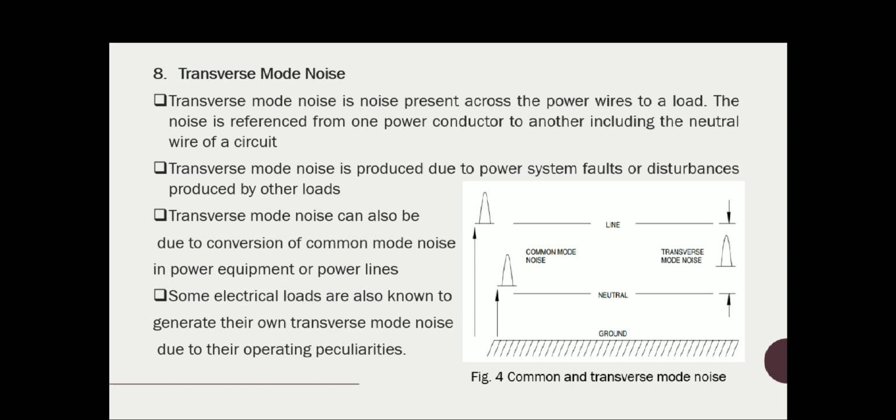Then transverse mode noise. Transverse mode noise is the noise present across the power wires to a load. The noise is referenced from one power conductor to another, including a neutral wire of the circuit. You can see in this particular figure the common and transverse mode noises. Transverse mode noise is produced due to power system faults or disturbances produced by other loads.